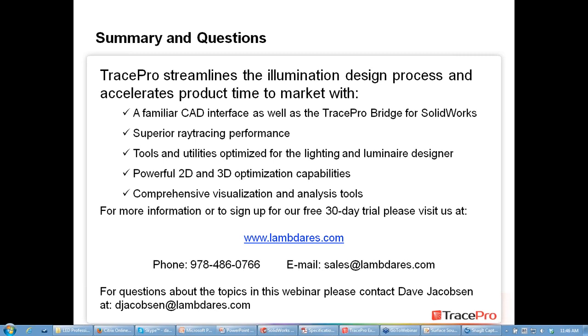There are some questions. For example, can you use ray files to model the LED output? You can. We have full support of ray files, both monochromatic and polychromatic, or multicolor. I mentioned earlier, a lot of times I will use a ray file for this type of application, but in this case, there wasn't one available. At this point, either it hasn't been published or the measurement has not been made. So I used the surface source property that we have. But yes, you could use ray files quite easily for the optimization.